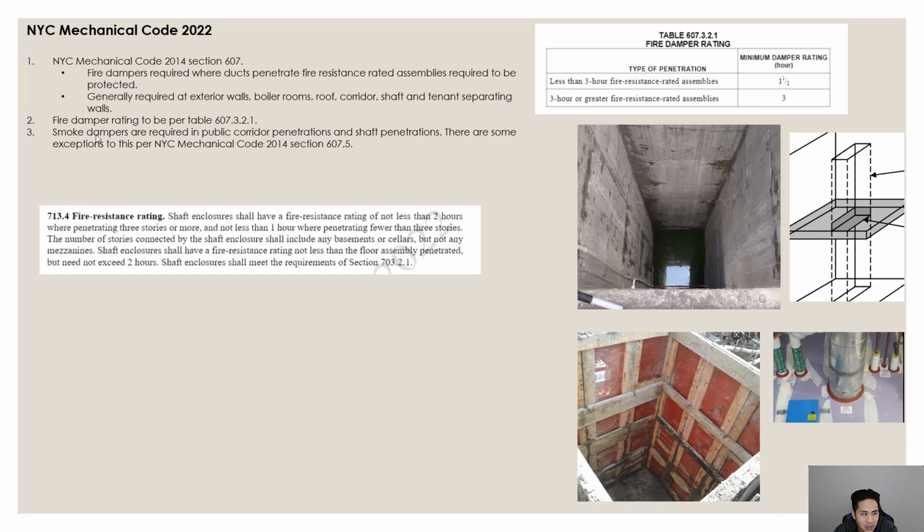A fire damper is something that operates all mechanically, meaning that it has a fusible link. And when there's a fire, it melts that link and it basically unloads the fire damper and it closes it. And that's how a fire damper works. So a smoke damper is more electronic. A fire damper is purely mechanical, operated.